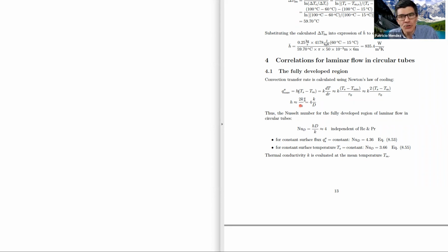But when we define the Nusselt number, because we tabulate convection coefficients as Nusselt numbers, the book does not have a list of convection coefficients. The book has a list of Nusselt numbers from which we can calculate a convection coefficient. And they do this not to torture anybody, but to have an enormous amount of generality. Tabulating things as Nusselt based on Reynolds and Prandtl, they can do this for any fluid and any size, as long as we match the limitations of the correlations they have.